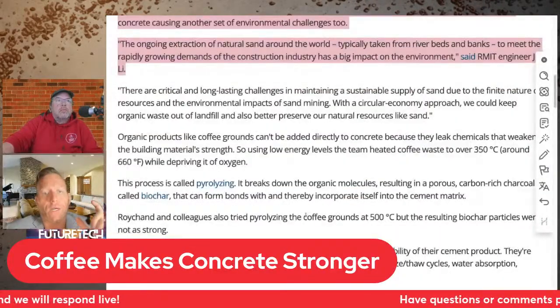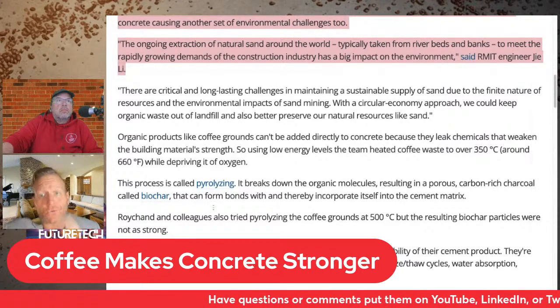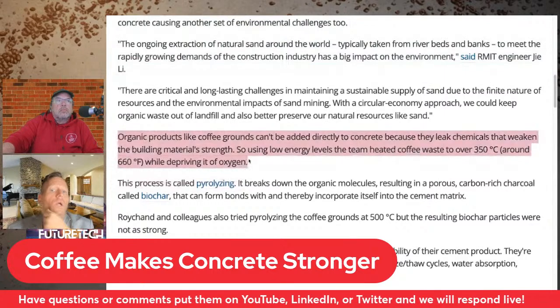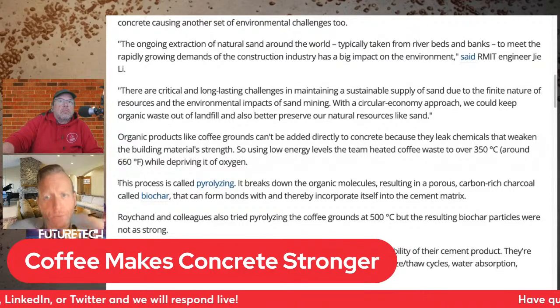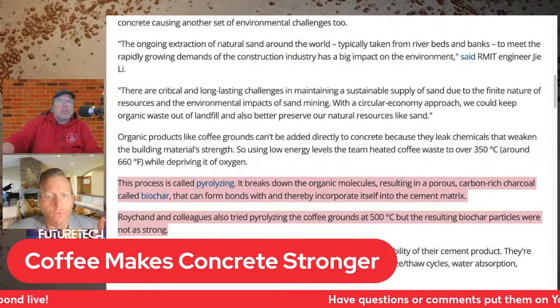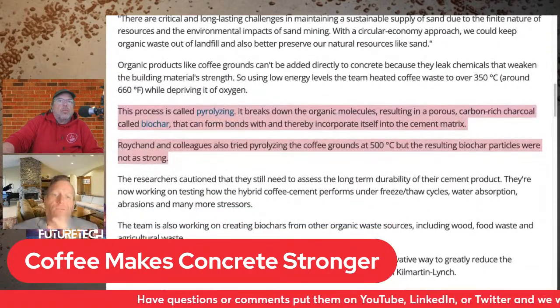Adding the coffee-derived biochar to the concrete increased its strength by up to 30% in testing. Biochar bonds with the cement matrix, and it acts as a reinforcement filler material, which is really cool. The strength improves as more coffee grounds are added up to a saturation point of around 5%